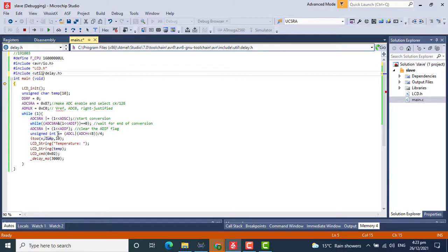integer x, and this value 4 is a specific conversion that is done according to the sensor we are using. After the calculation, this value turned out to be 4. This includes the whole calculation, taking the actual value from the ADC0 pin, dividing it over a 10-bit ADC converter and multiplying it by its sensitivity. After the conversion is done, the data is then displayed on the LCD that is connected to the microcontroller.